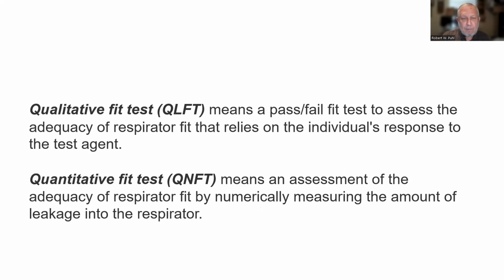Qualitative fit test, QLFT, means a pass-fail fit test to assess the adequacy of respirator fit that relies on the individual's response to the test agent. Quantitative fit test means an assessment of the adequacy of a respirator fit by numerically measuring the amount of leakage into the respirator. And that's basically the basis for your difference in your definition, generally speaking, of qualitative and quantitative.